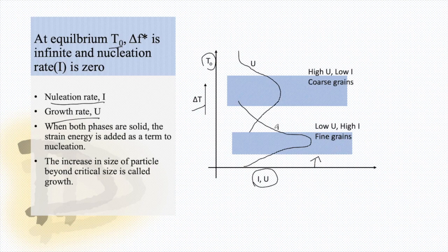we start to form the nuclei, and nucleation is maximum at some point in a range, where the growth is very low, and growth starts to rise to a maximum at some point at a higher temperature range, and then also starts to drop down to a lower value. This range 1 is the point where we get high nucleation and low growth rate.